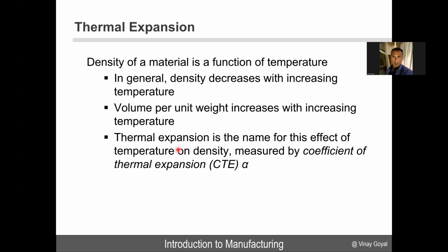For example, if you have a metal bonded to a composite, the difference in coefficient of thermal expansion as they go through higher or colder temperatures can cause a residual stress or thermal stress induced by the mismatch in the coefficients of thermal expansion of the respective materials. That can cause stress, that can cause cracking. That's why understanding thermal expansion is important in a manufacturing process.